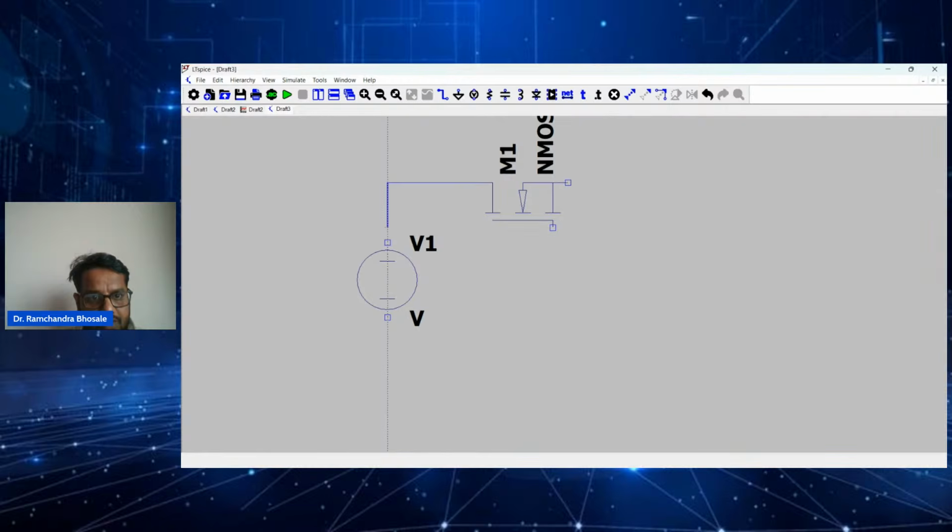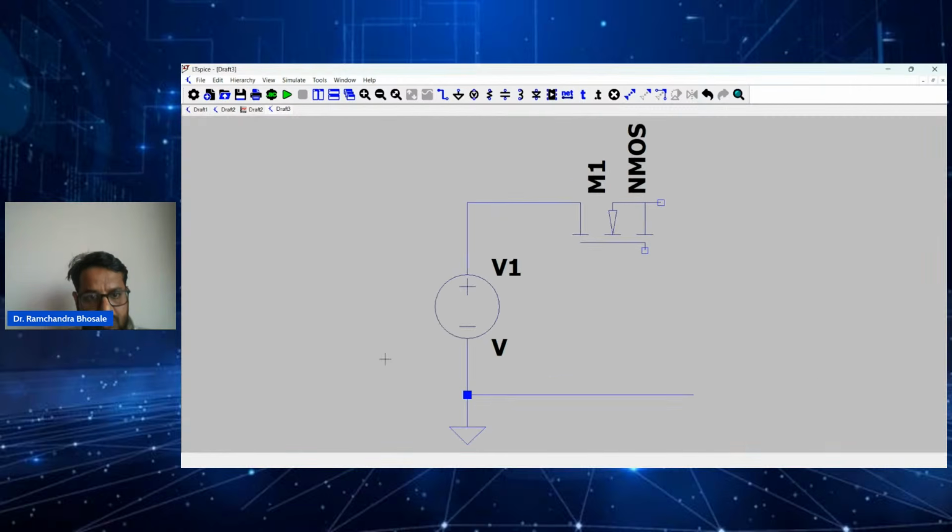First, what we'll do, we'll check this much circuitry, whether it is behaving correctly or not. Okay, so here, if I'm giving 12 volt, here we should not get any voltage, like the MOSFET is not turned on, right? So let us see. We'll select some MOSFET also. We'll go to MOSFET, and let us take a 40 volt MOSFET. Okay, this one I'll take.